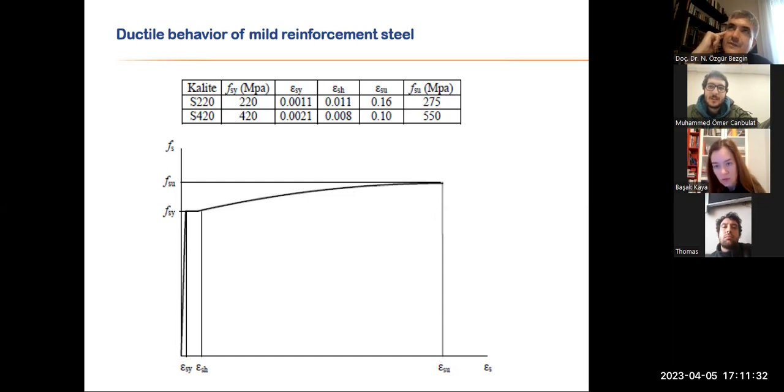The R value has to do with the type of the system, like a shear wall has a different R value. Reinforced concrete design has a different R value. The R value is basically the ductility of the system, but the materials and the structural system affect the whole ductility, of course. So if there are only simply supported beams and columns in reinforced concrete, this is a different ductility than a steel building, like a moment frame. So it's another ductility. It differs. It depends on the material. I agree.